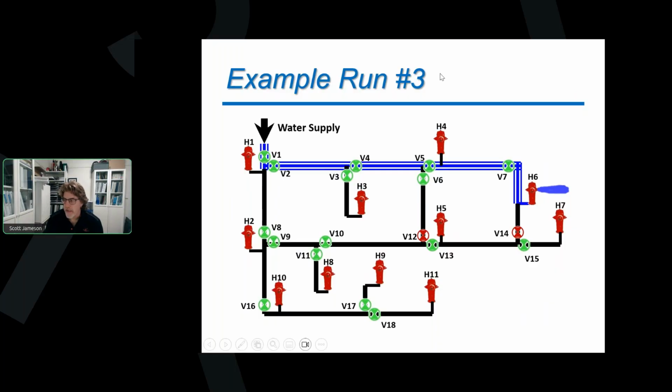So, if I did have valve 6 closed, that would hopefully prevent that, and they would be getting clean water coming around on their normal flow around the back side of that loop. But that's one of these ones that we're going to have to maybe experience out in the field and adjust the plan later, right? So we need to be open to these changes. But I've written out another flushing run.